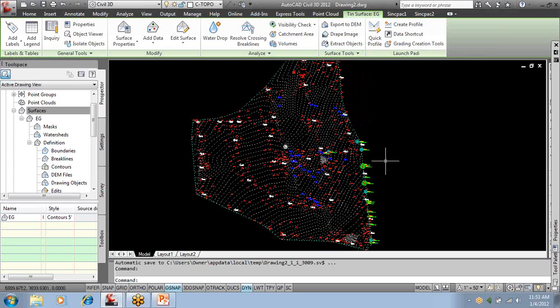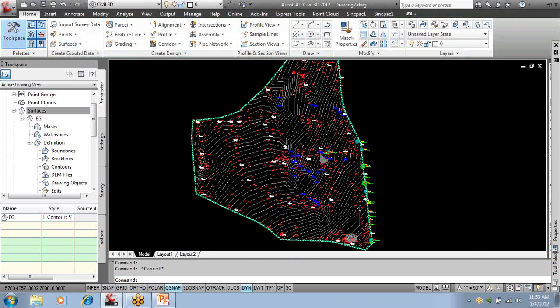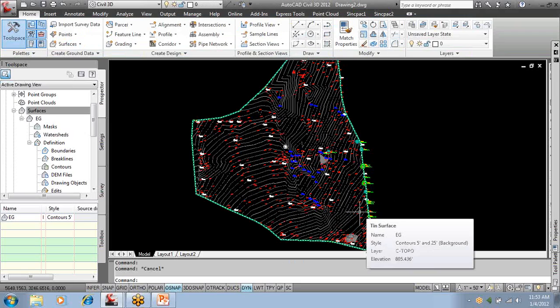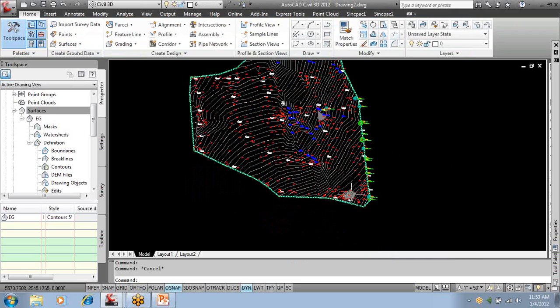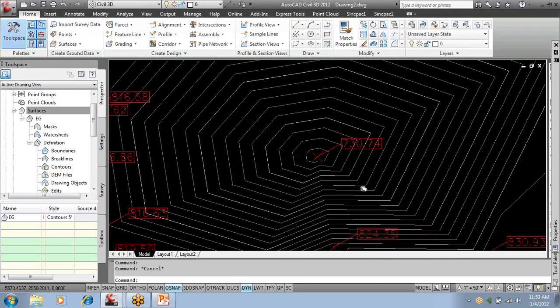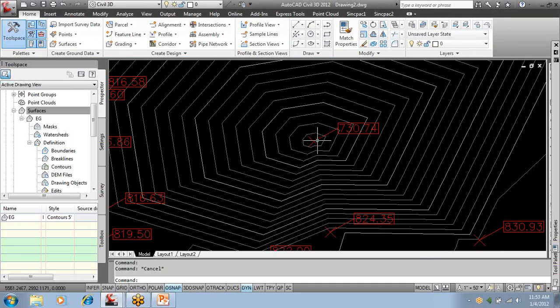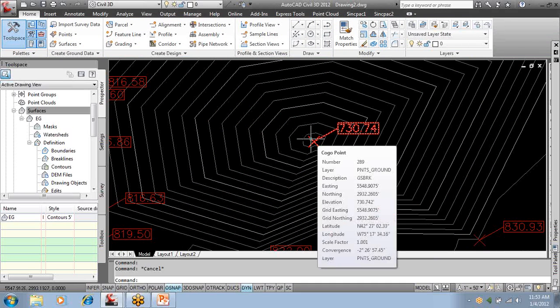You don't want them as polylines in Civil 3D because it'd be like exploding them, and then it dumbs down the program. I want them as contours, and I'll show you. I want them as a surface object in here. I want to display that object with style. The reason for that is if they're contours, you don't get to do different things like this. So this is how you utilize the program a little bit.